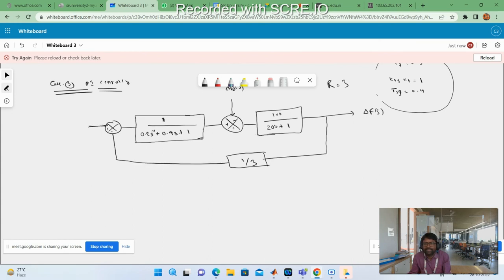So this is the plus, right? And what about the delta PC? Here is the PI controller. It's not a free governing operation. If it is a free governing operation, delta PC equal to 0. That means your speed changing position is fixed. You are not opening or closing the valve, right? But now it is case 3. You are controlling your speed changer accordingly based on your frequency deviation.